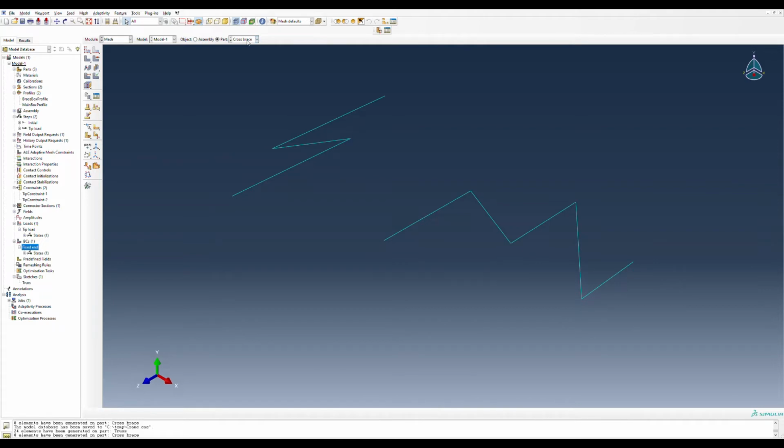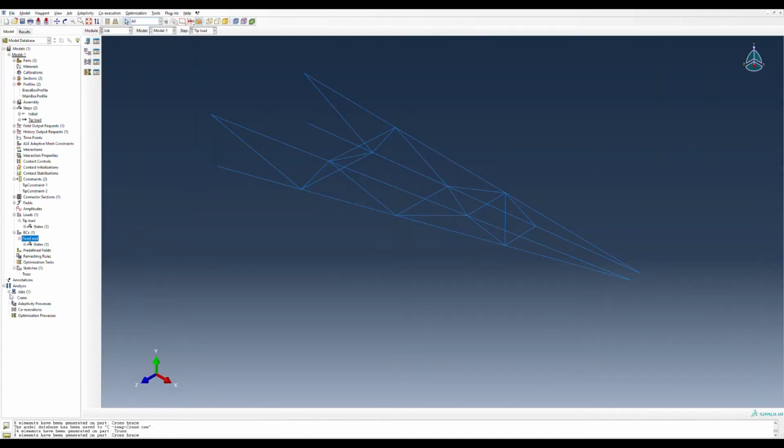Then finally, for this problem, what we need to do is go to our job. We have our job over here, crane. What we're going to want to do is a data check. And once we do our data check, it will say results. Once the data check is fully complete, you're going to want to hit your results and it'll